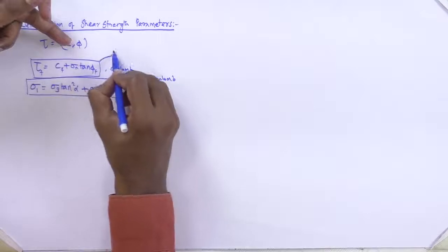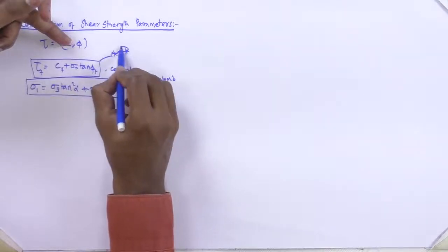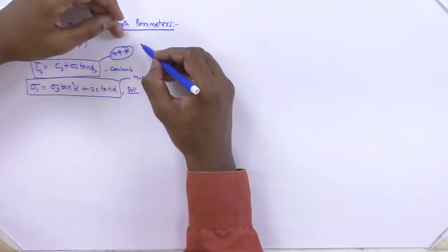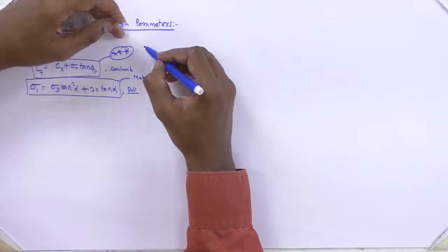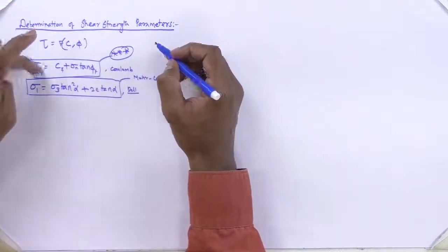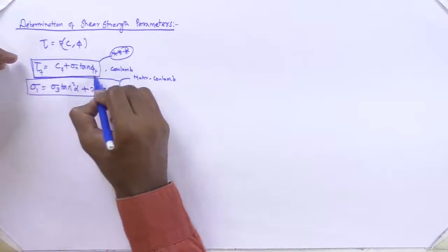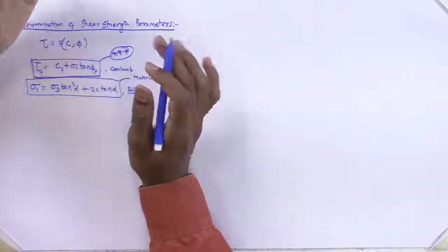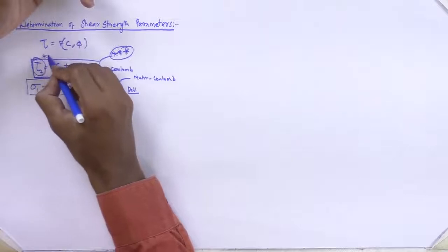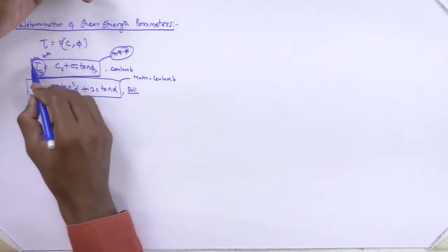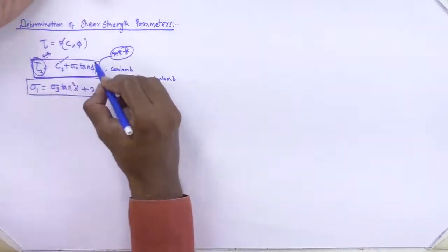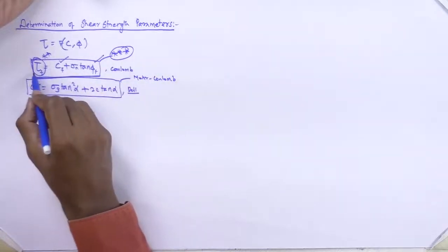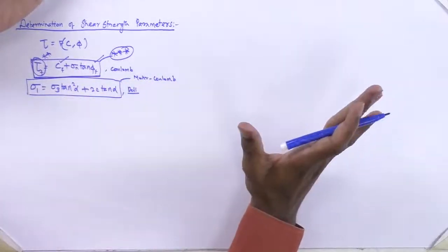So this is our major concern, as I explained, in the applications of foundation failure, slope failure and retaining wall failure. This is like a mantram. This equation plays a role in design. So tau is our concern. In order to find tau, we need to find C as well as phi. Then we can find tau f, and we can start our design works.